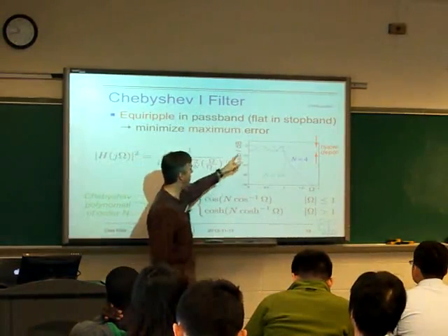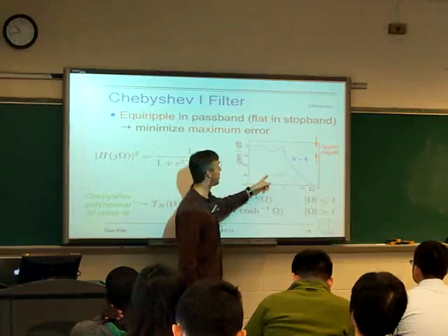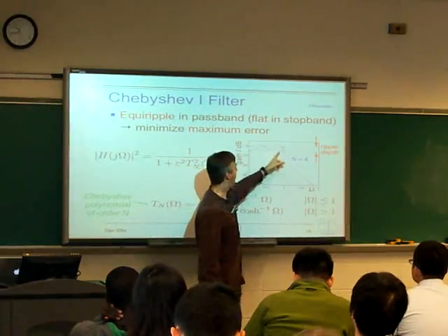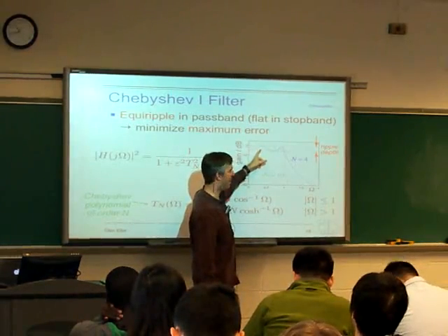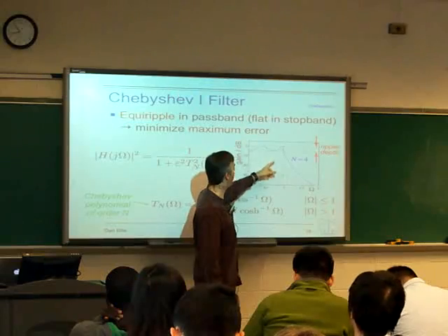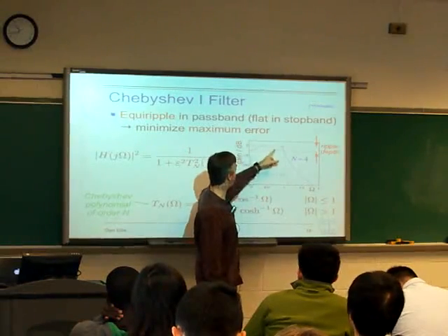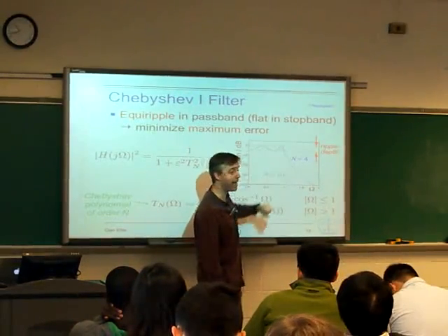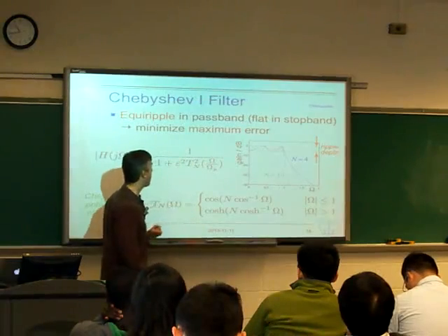The number of ripples that we see is going to relate to the order of the filter. For a low-order filter, we get about n on 2 ripples in here. For a higher-order filter, we get more ripples, but we also get a more rapid decay as the filter goes out, which is a better low-pass filter.